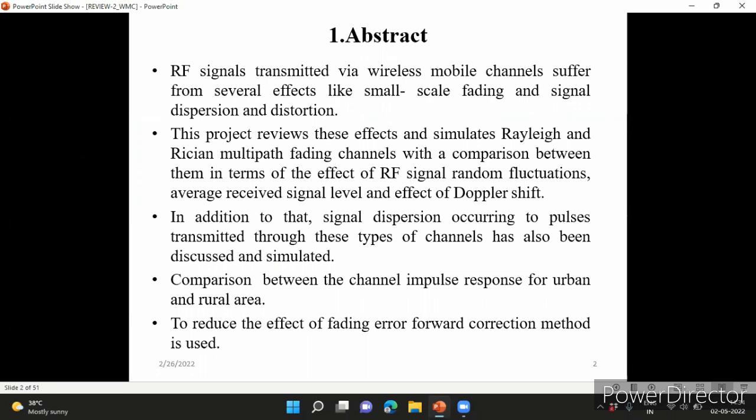But there is a problem: if something happens to the sent and reflected signal, the signal is completely lost and would never be received at the receiver. So the same signal is sent by multipath. Through multipath the signal reaches the receiver, and the receiver takes the vector sum of all these different paths and deduces the information that was actually sent.